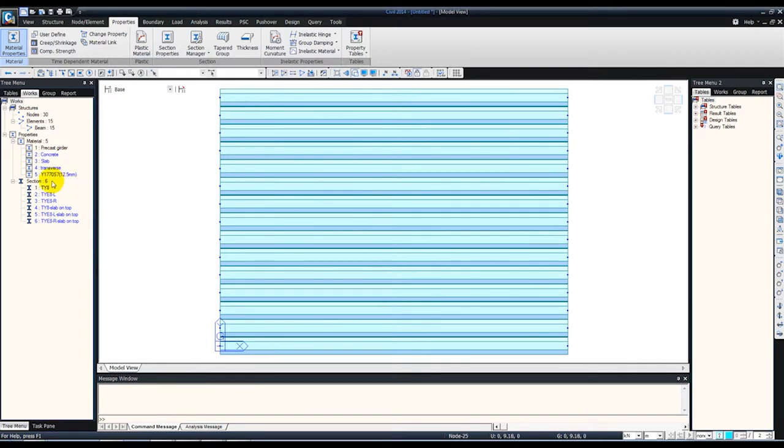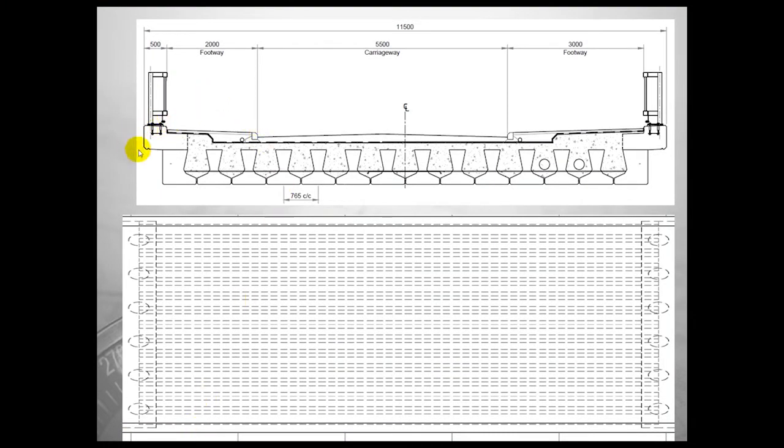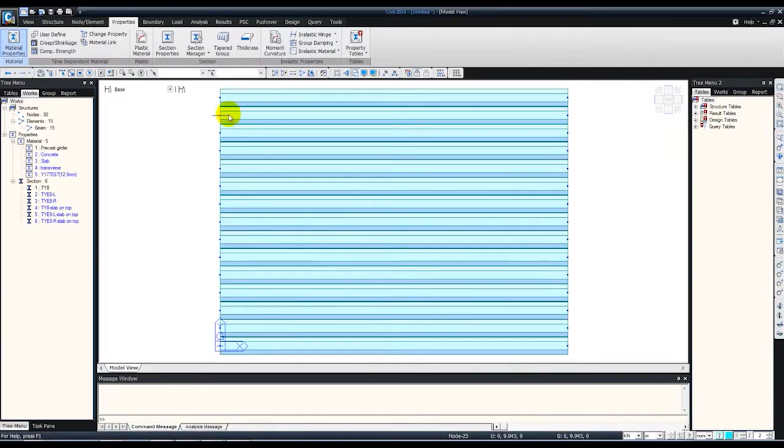Okay, now we also have some precast edge beams. We can model them, or we can leave them, just model them as loads. So we have some precast edge beams here. Either we can model them as actual beams, or we can just model them as loads eccentrically applied to the edge beams. So what I'm going to do is just model them in this case.